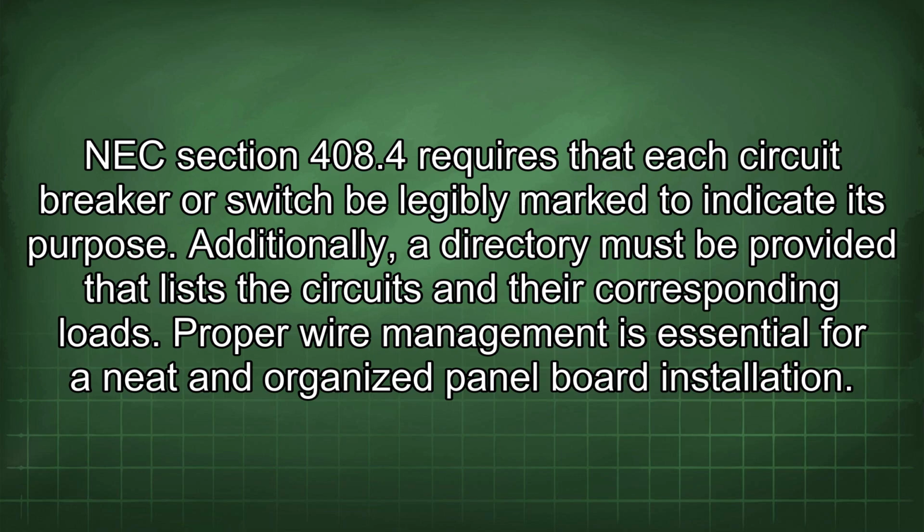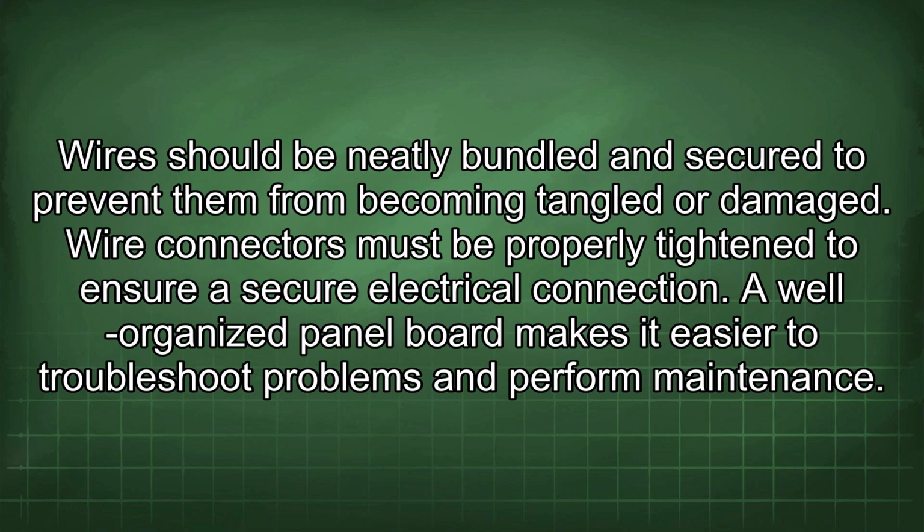Proper wire management is essential for a neat and organized panel board installation. Wires should be neatly bundled and secured to prevent them from becoming tangled or damaged. Wire connectors must be properly tightened to ensure a secure electrical connection. A well-organized panel board makes it easier to troubleshoot problems and perform maintenance.